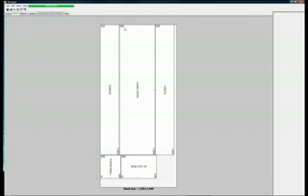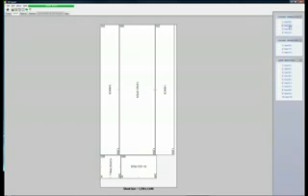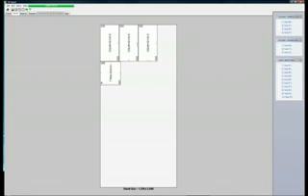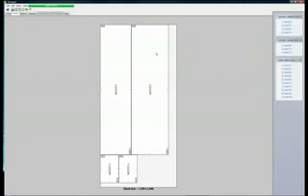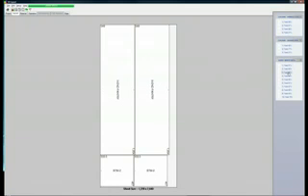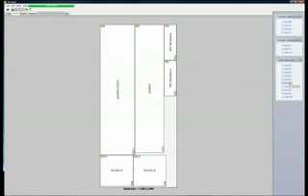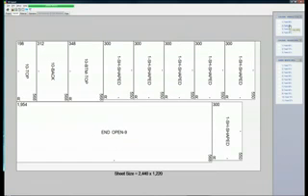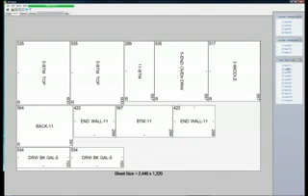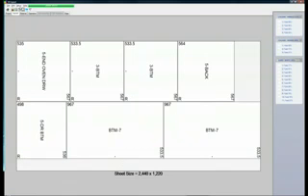Doesn't take very long, it runs through each category and then gives us an illustration of the cut panels, which can be now printed. The edging information is shown on the printed lists. The edges that to edge are defined by the little black dots. Okay, so we're getting quite detailed information, and we can recalculate to allow for grain material. We can specify the sheet to be trimmed prior to being cut.